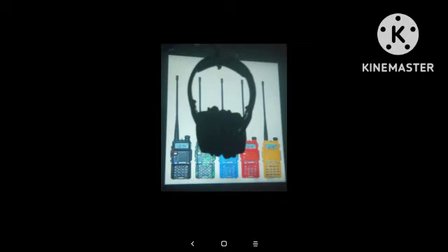Number 35. If you were to cut a half-wave dipole for 3.75 MHz, what would be its approximate length? 38 meters or 125 feet. Number 36. Why is a Yagi antenna often used for radio communications in the 20-meter band? It helps reduce interference from other stations off to the side or behind.